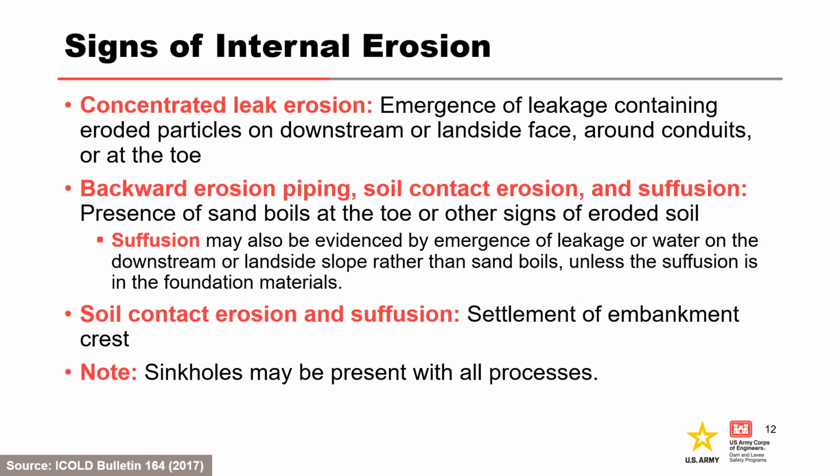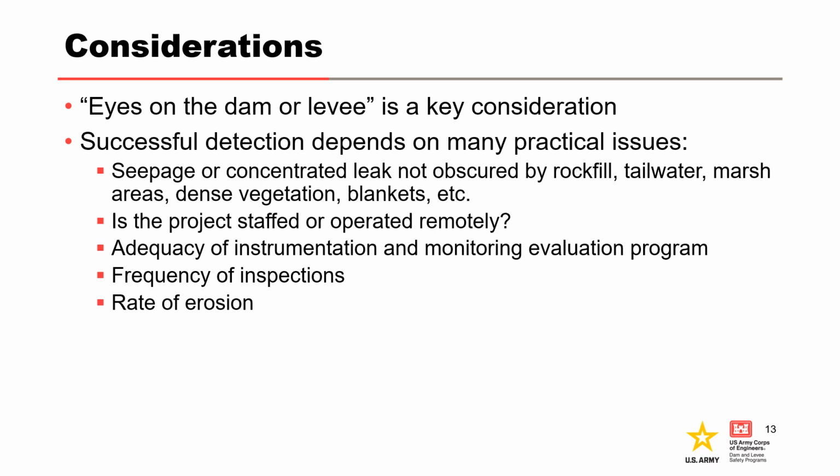For soil contact erosion and suffusion, crest settlement can occur. Sinkholes can occur with all internal erosion processes. And the sinkholes may be relatively benign, like from internal migration and suffusion, or they may indicate the erosion has already progressed and the time to failure may be small. Seepage or concentrated leaks may be obscured by rockfill, tailwater, marsh areas, dense vegetation, blankets, etc.